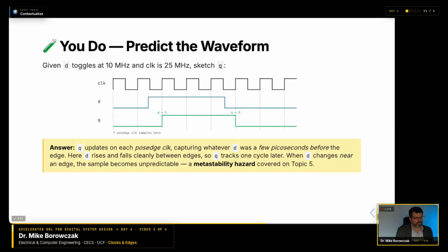So we get that output high, so Q goes high, and it stays high, all the way until we get a positive clock edge, which is about 3 from the back here, where D is 0. It's not until the clock goes high and D is 0 that we then get an output of 0.